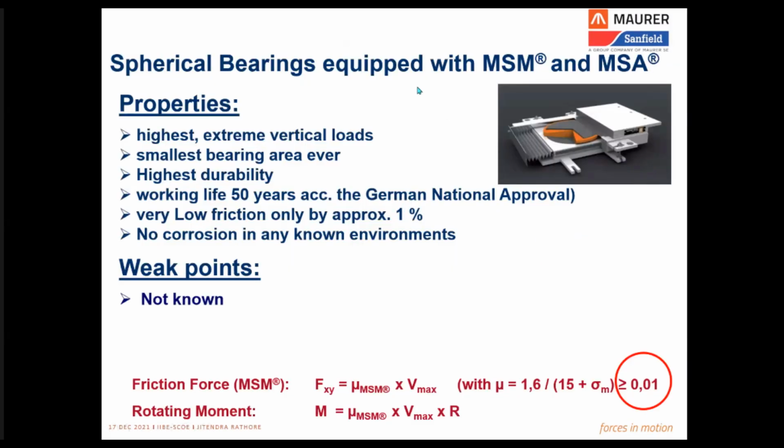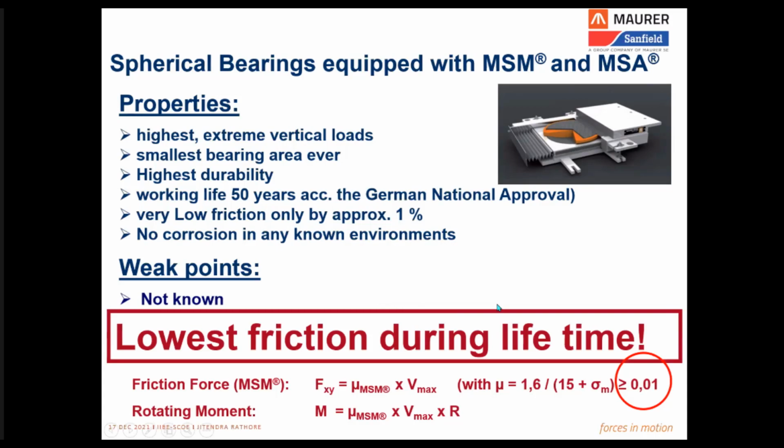So the innovation of this aluminum alloy and its use in the bridge bearing not only eliminates the corrosion concerns, it is also a very good load bearing element, so it doesn't compromise the load bearing capacity of the bearing, and also it offers a very low value of friction when it slides against PTFE or UHMWPE. So this innovation of sliding alloy helps the bearing achieve the lowest value of friction, so the performance of sliding is further improved and the concerns of corrosion are totally eliminated.